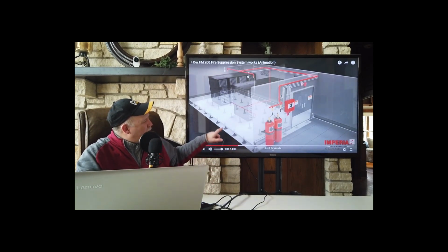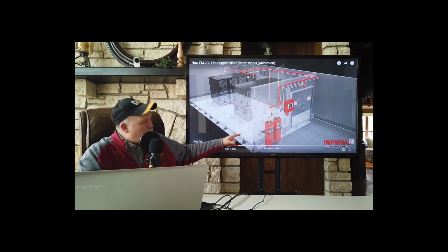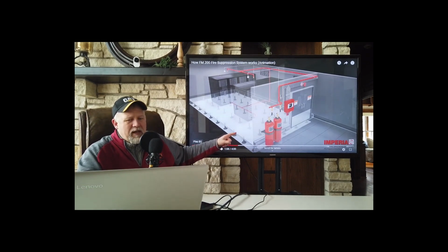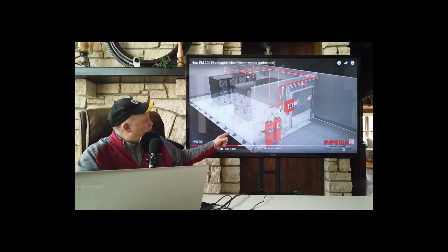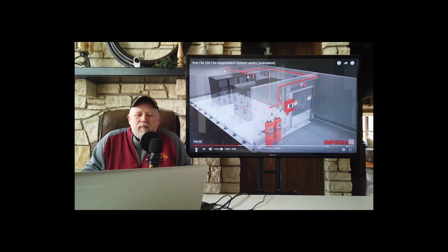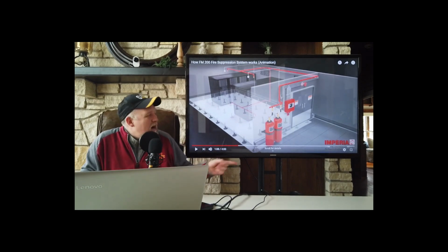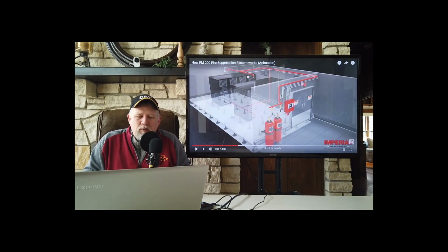This is going to be full of all of the telecom wires going to these servers. This will also be where they pump in cool air from the air conditioning system. So there's also going to be discharge nozzles below here as well. Something else that this control panel will do is shut off the air conditioning system and stop air from recirculating through here, because we don't want to fan the flames and we don't want to spread the smoke that fire is going to cause either.